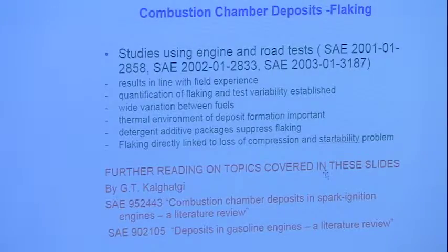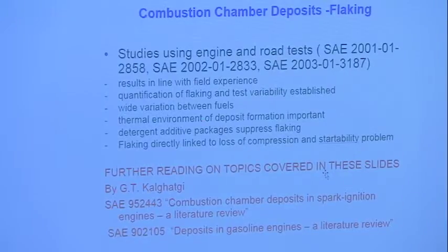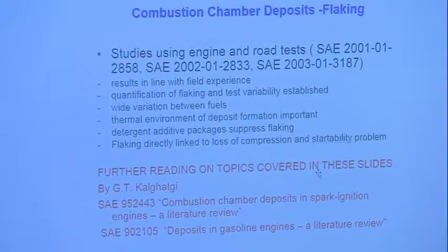And we found that there was wide variation between fuels. And it was definitely dependent on the cycle the engine ran, how the deposit was formed. So the thermal environment for deposit formation was important.